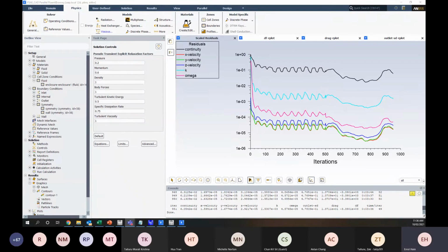So I sort of asked this, but I appreciate further clarification. For validation to select the most appropriate turbulence models, would you recommend using 2 different near wall mesh resolutions? Okay, so in this case, if you're tossing up between a y plus of 1 and a y plus of 30, in terms of using it for a validation case, if you have enough computation power to resolve to a y plus of 1, then resolve to a y plus of 1.